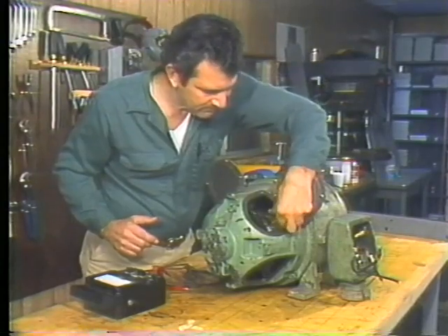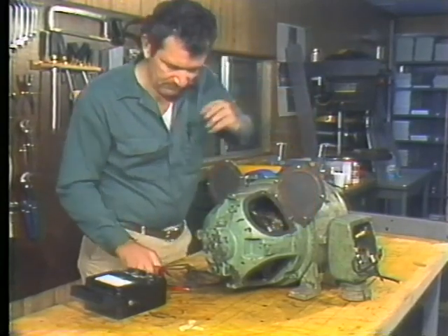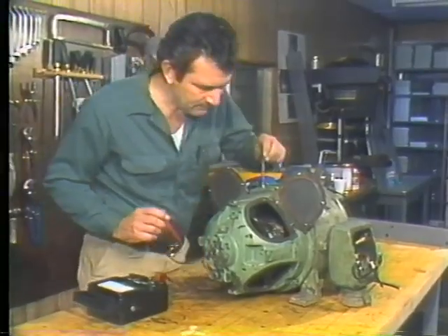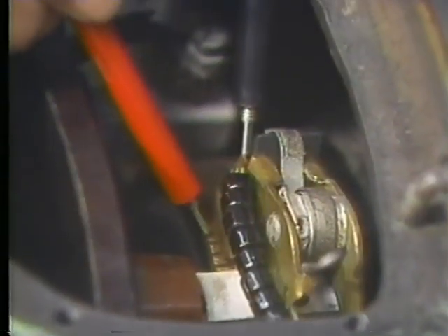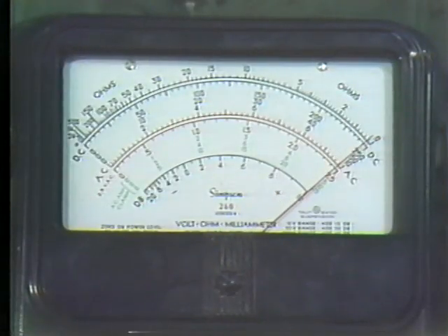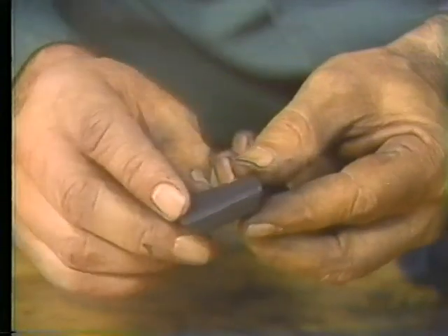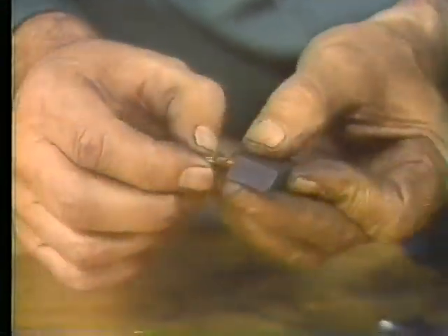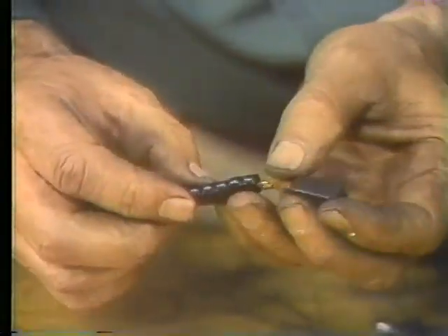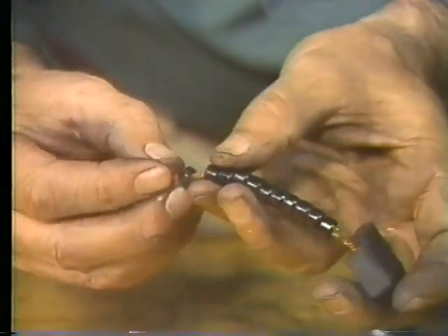Okay, now we have to repeat this brush check again on the other side. It's probably still okay. All right, the brush is back. The tension's adjusted. Yes, we've got a reading here. Well, we've got to do a more detailed check on the questionable brush. The procedure is check its length, pigtail, contact surface.